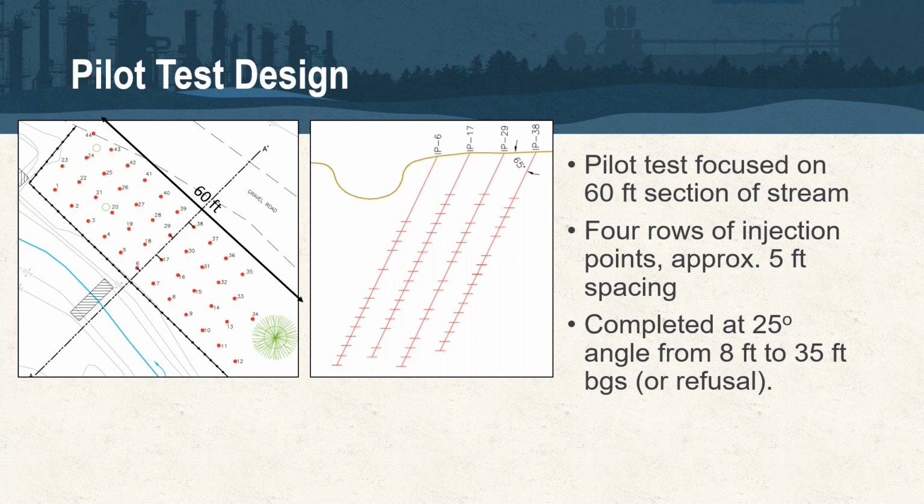They help us identify extent, vertical and lateral extent, but they don't provide quantitative information. So you can't tell me if you're getting an ECD or XSD response or a PID response that equals X micrograms per liter of PCE in groundwater or soil, right? And so we always have to back up those surveys with a good amount of soil sampling.